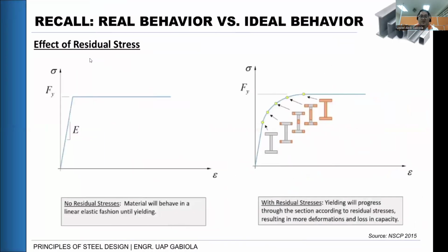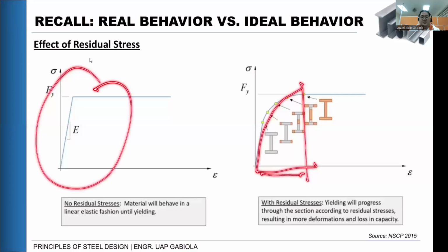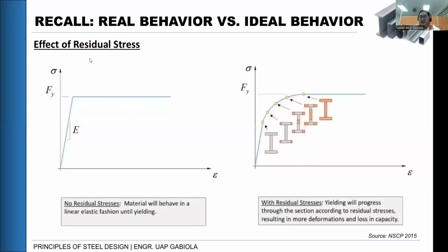According to this diagram, this is the ideal and real behavior of our column. Before it attains the yield strength required for our design, it takes a number of multiple strains compared with the ideal one, so it takes longer to develop, and that causes a reduction in the performance of our column.